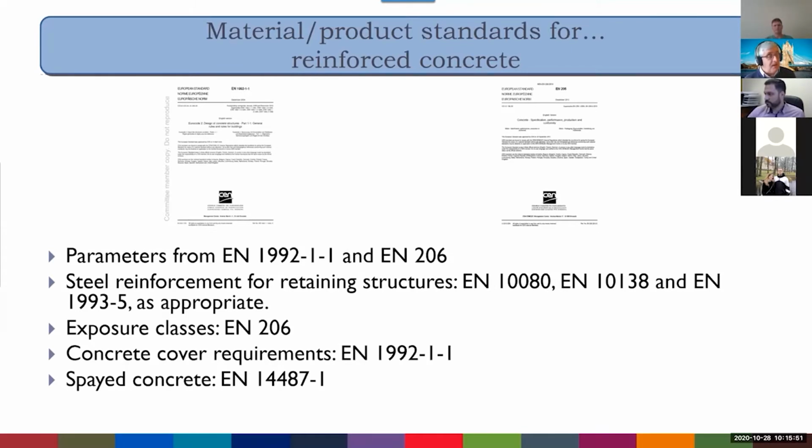But that has now been rectified, and the people writing this standard have listened to ground technologists who have explained that the concrete that we use in the ground has to be different from superstructure concrete because we've got to get it into the ground. And there's the issue of the flow, and the issue of the durability in the ground. There's a whole different set of technical requirements. EN 206 now covers that, so I'm quite pleased about that.